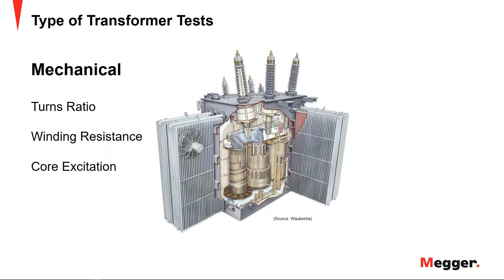So if you leave the setting to auto voltage, the test set looks for the optimum voltage that should be applied for a given transformer so that you get the best possible results. So I highly recommend starting the testing in the auto mode, because that would give you the most value out of your testing.